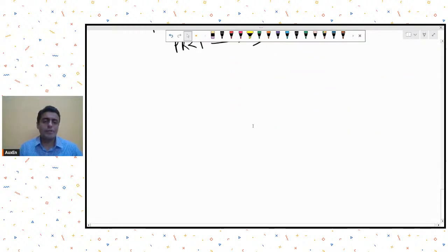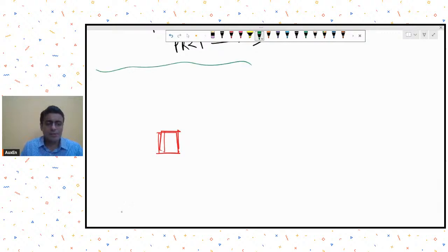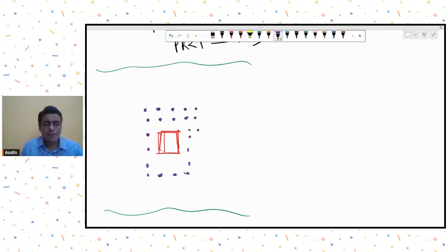Now, how do we provide punching reinforcement? Punching reinforcement can be provided in different configurations. I'm not showing you the calculations right now, but one of the ways: if this is my column in plan and I have a large slab, remember this is without drop, I can provide vertical links like this in the periphery, arranged like this, and then this type of parallel link system will go till a certain distance.